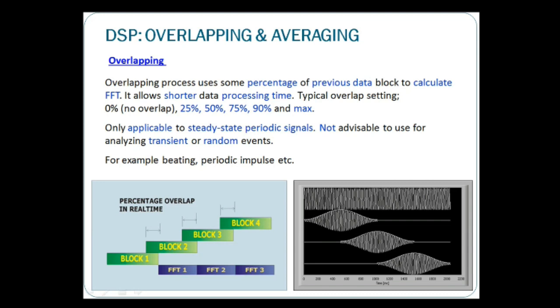This average is related to the number of samples in one block that we decided earlier. If we want to convert signals to frequency, we need to decide the number of samples in one block to process these FFTs. The acquisition time is based on your sampling rate and block size. So you have to wait.